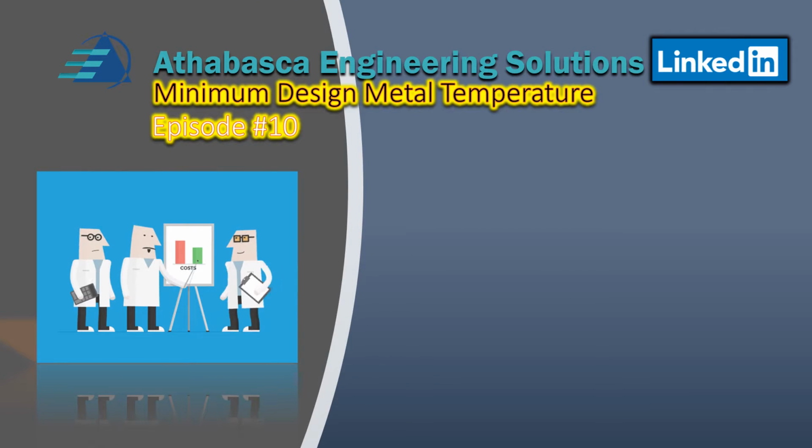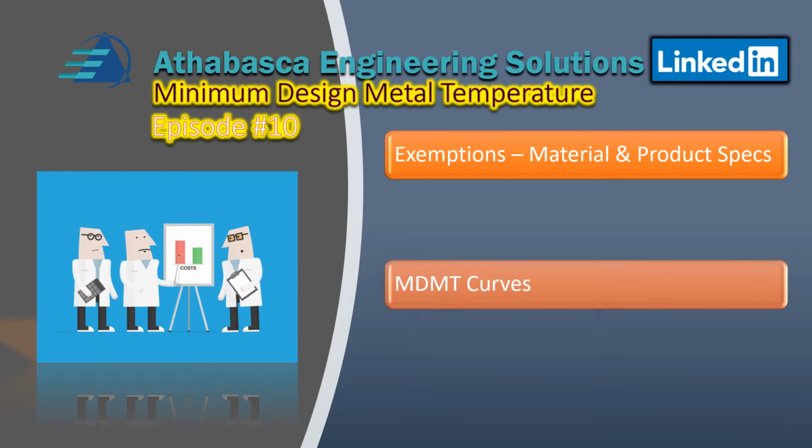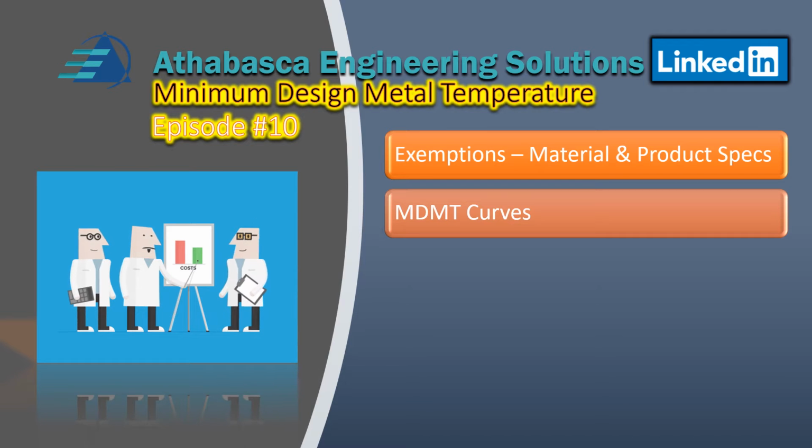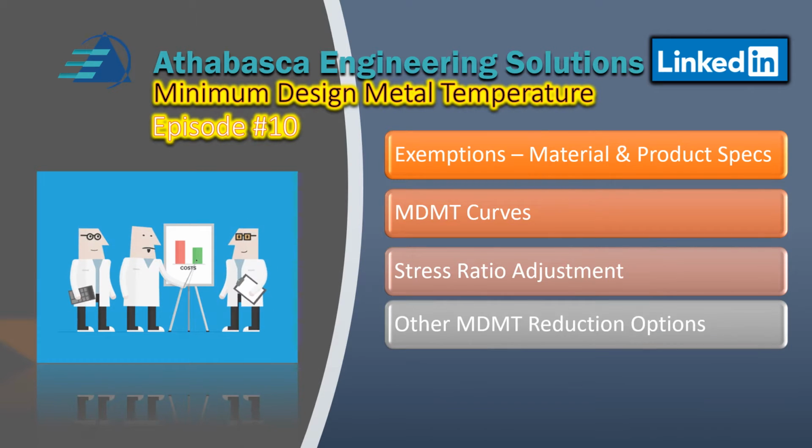We're going to be working on episode 10, or part 2 of Section 8 Division 2. In this presentation, we're going to talk about exemptions of materials and product specifications. We talk about MDMT curves. Then we're going to talk about the stress ratio adjustment, sometimes also called the coincident ratio. And then the other MDMT reduction options that are available. With Section 8 Division 2, there are more options available than Division 1.